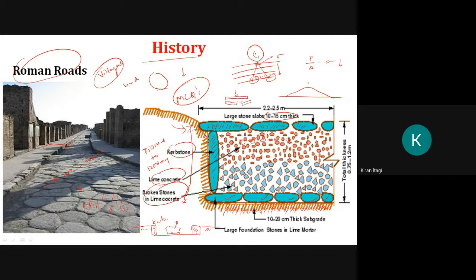Okay, our road will be like this. Whenever the rainfall happens, the rainwater will automatically be drained off to the side drains. Why we do this is to protect the substructures. If the water percolates inside the pavement, it will damage the substructures or the layers below.